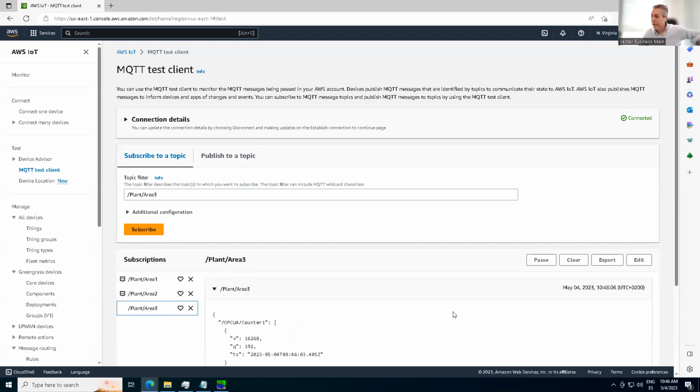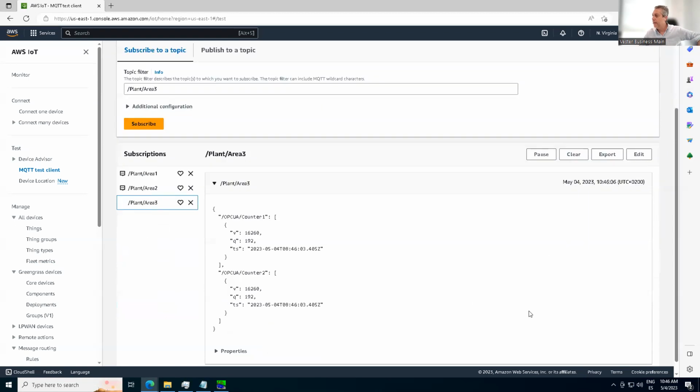There we go, OPC UA, again, every 5 seconds. So all these three publishers are completely individual. Of course, I can get all my tags inside the same publisher, no problem. This is just a way to show how I can publish different data at the same time, using different topics, different frequencies, different formats, etc.